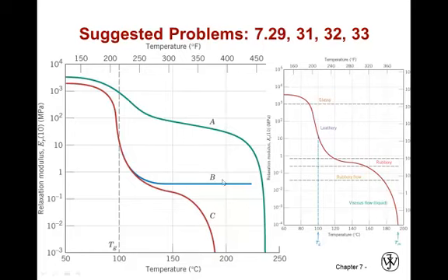Cross-linked at 180 C, that's B. So notice the difference between the amorphous and the cross-linked. The cross-linked will stay at about this elastic modulus, still pretty low, but it's going to act very differently at the same temperature as the same material, polystyrene. This one just happens to be cross-linked. So because it's cross-linked, the polymers are not going to slide with respect to each other. They're not going to deform in the same way as the uncross-linked material, the amorphous material.